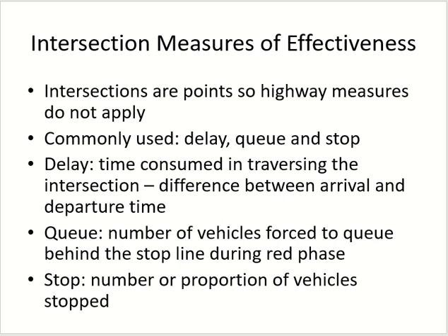These things work on highways because on highways we have speed and all these things. But on intersections, these measures cannot work because on intersection you have a control device, stop sign, roundabout. People are supposed to come and stop. Either you force them to stop or they have to stop for safety, right? So when they stop, their speed is 0. Their flow rate is 0. Their density is non-zero. So it's maximum.